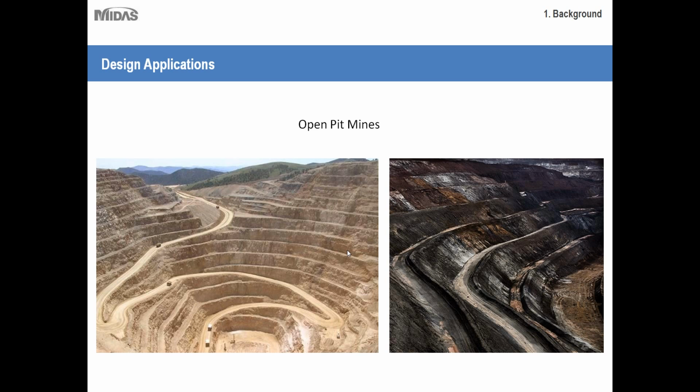So if you're doing slope stability with rock types, faults, shears, and joints are things you really need to look out for because they can be very deceptive. I mean, if you have a fault line hidden behind one of these slopes, then an excessive amount of pressure could easily crack them. So that's something, once again, that you'd have to look out for when working with rock.